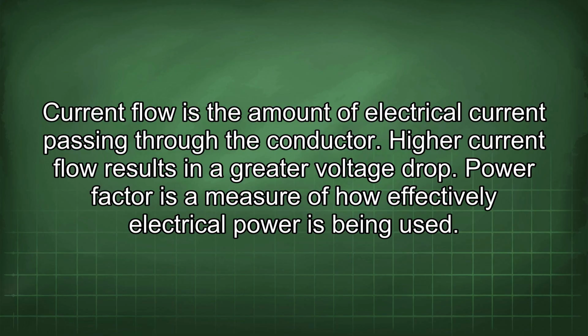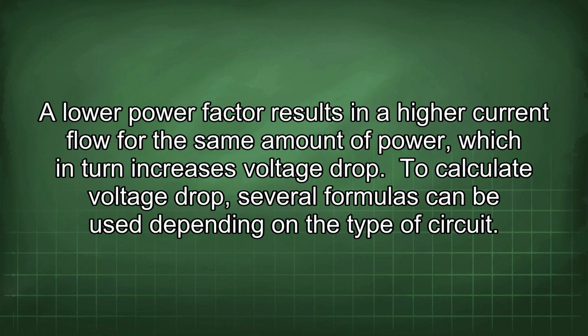Power factor is a measure of how effectively electrical power is being used. A lower power factor results in a higher current flow for the same amount of power, which in turn increases voltage drop. To calculate voltage drop, several formulas can be used depending on the type of circuit.